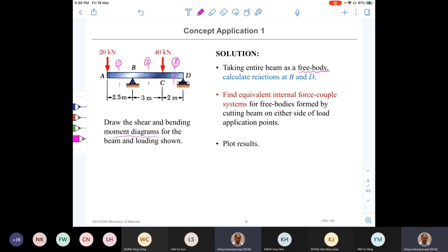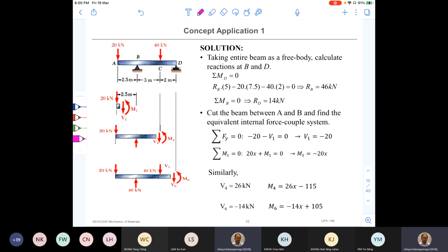But you don't need to do this later, because once you learn the basics, we can find an easy method of constructing the bending moment diagram and shear force diagram. But I want you to now use the fundamentals. Okay, let's start working on this one. The first step is to draw a free body diagram. So what I'm going to draw here now is the FBD, by drawing the reaction forces, and identify this reaction force as RB and this one as RD.